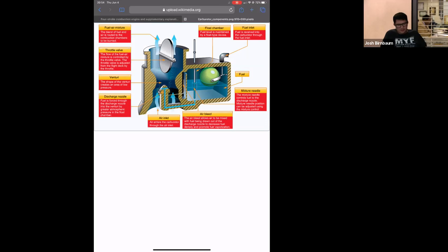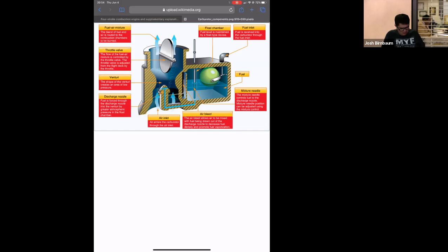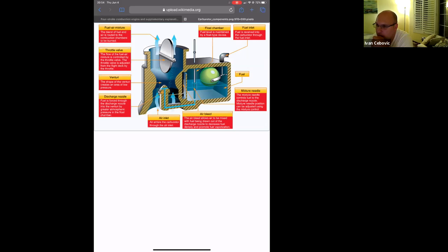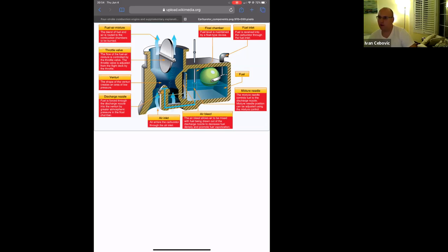I think the ones that I've seen are OAT gauges, because the J vent is on the left side. Yeah, the J vent is for the fuel, and the right side, if you're talking about a short little stubby metal pipe with holes, I think that's the OAT. It's aluminum in color, it's unpainted. Yeah, that's the OAT, so it's just a measuring tool. It's just the outside air temperature. Okay. It looks like a vent to me. That's why I said it was a genuine question. I wasn't too sure.